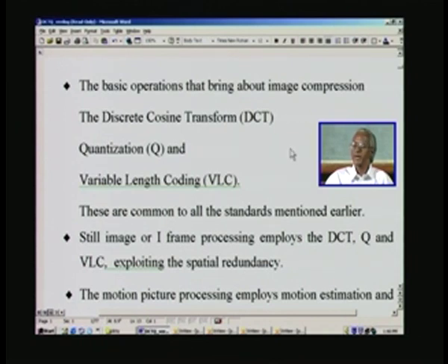These coefficients pack varying energy of the image in different coefficients. For example, the very first coefficient stores 8 times the average of the image information, and the rest of the coefficients, namely 63 coefficients, store only the balance, and this is followed by quantization.